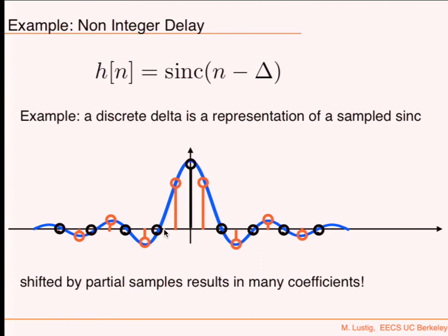Changing the sampling rate is never going to be ideal unless you use perfect filters, which are going to be infinite impulse response. So there's going to be some implication about changing the rate of a signal, especially if your signal is small and you want to change your rate. There are going to be all sorts of edge effects if you're using large filters. So you've got to understand this.